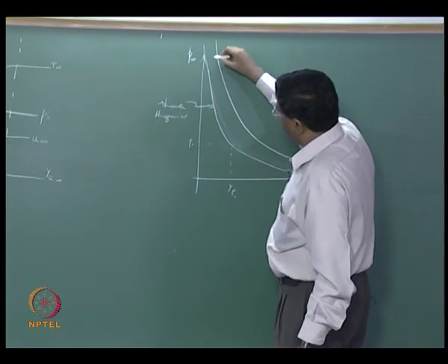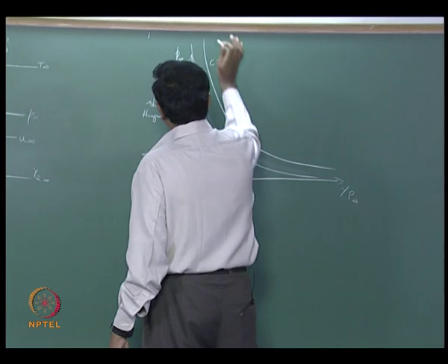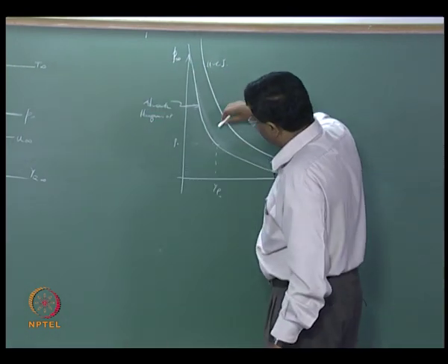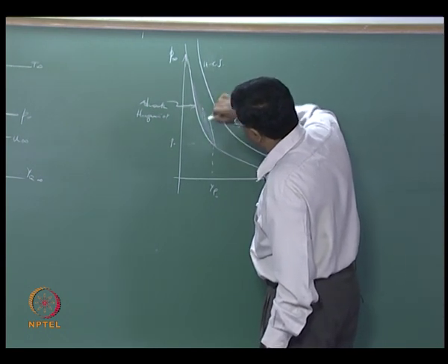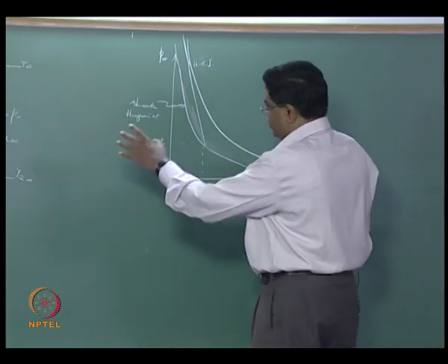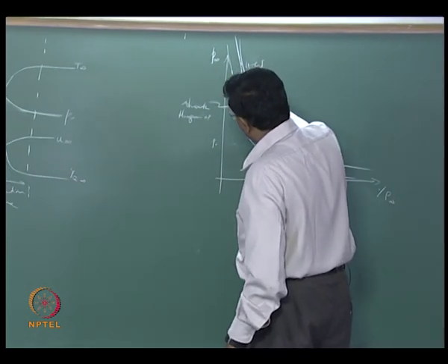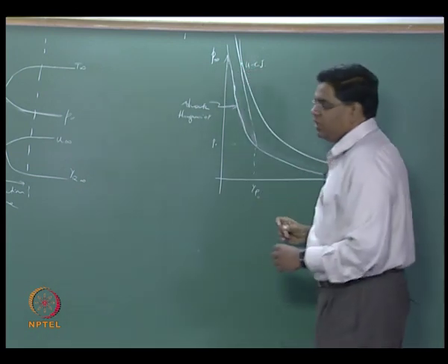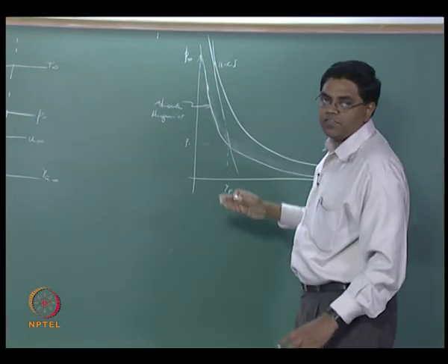And we are looking at the Chapman-Jouguet wave, so that is the UCJ point, and that means you are looking at a tangent Rayleigh line to the actual Hugoniot with the full heat release, but then we are looking for how you are trying to locate your point between successive Rayleigh lines intersecting successive Hugoniot curves for different q.